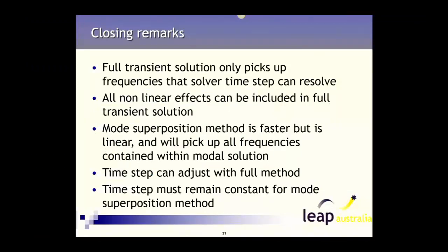Alright, so with the mode superposition method, it's linear, but it can be much faster to solve. The way we determine what frequency content we capture with the mode superposition is based off the frequencies in our base modal analysis.